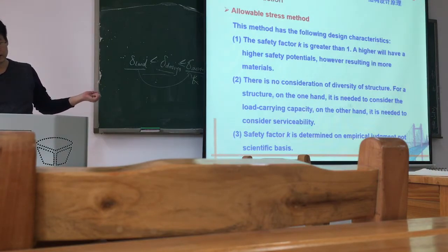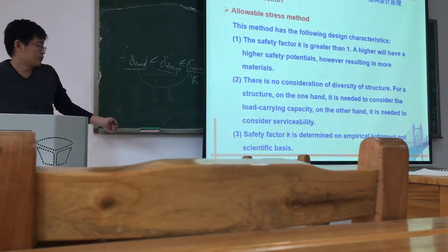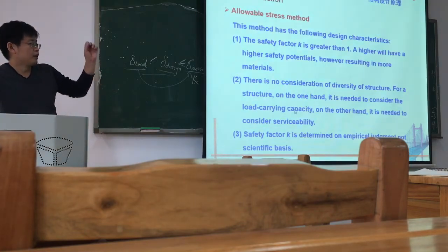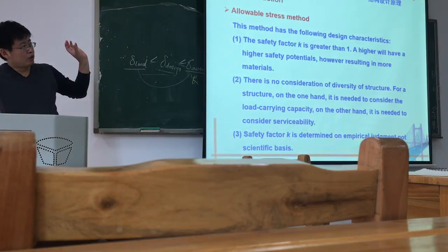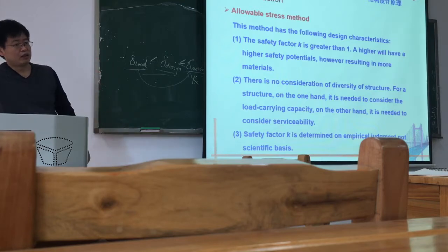For a structure, on the one hand, it's needed to consider the load carrying capacity, and on the other hand, it's needed to consider the serviceability. So what do they mean? Load carrying capacity and serviceability are different situations. Load carrying capacity means how large a load this structure can bear or resist. Not stress, yeah, the force of the load.